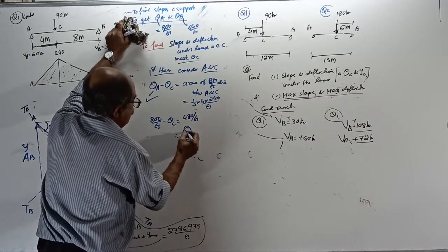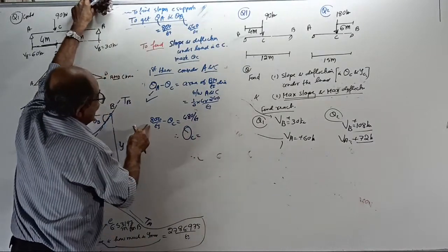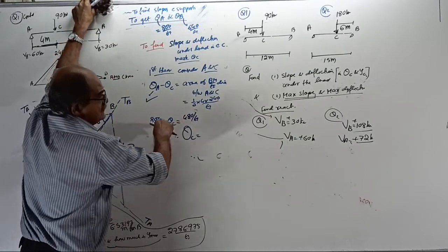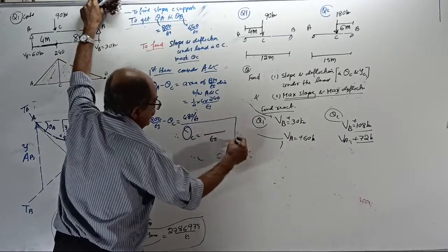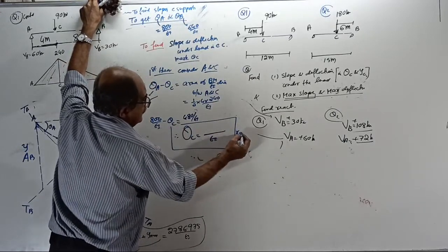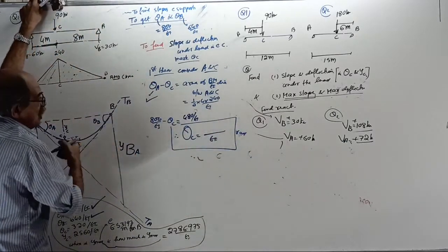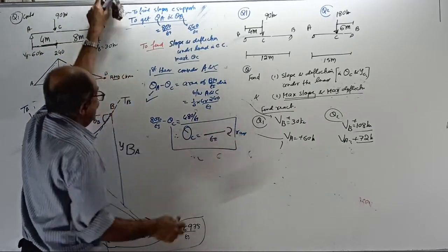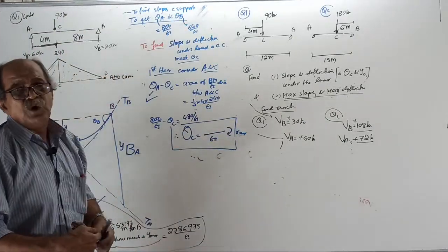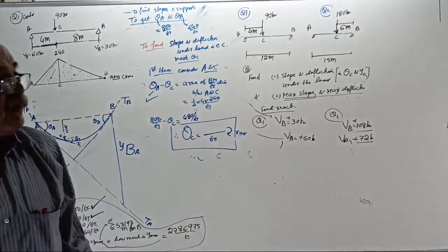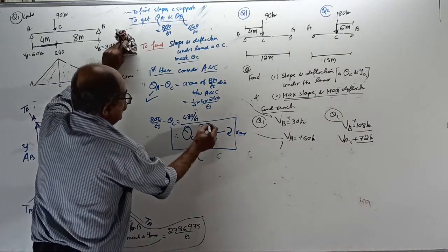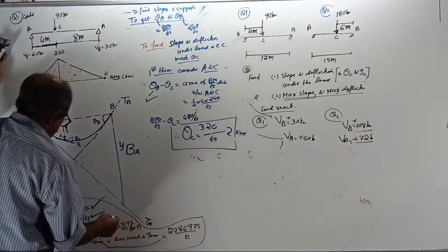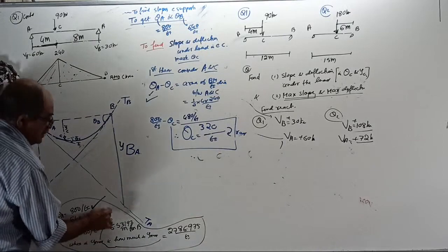Therefore, slope at C equals 800 minus 480. Theta C will go that side. Slope at C will come as something by EI radians. See the direction? It is clockwise direction. From 800, subtract 480. It is 320 by EI radian. Oh, my next answer also is correct.